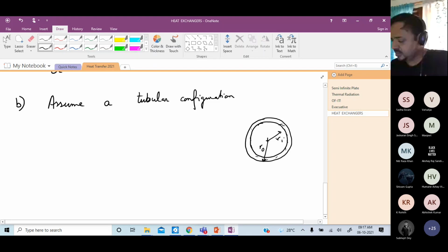So what I will write is 1 over U_i A_i. Important. 1 over h_i, plus, as we know, 1 over 2 pi k L log r_o over r_i.